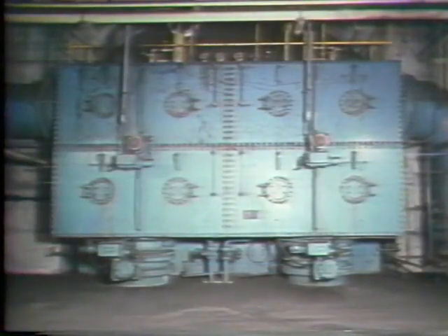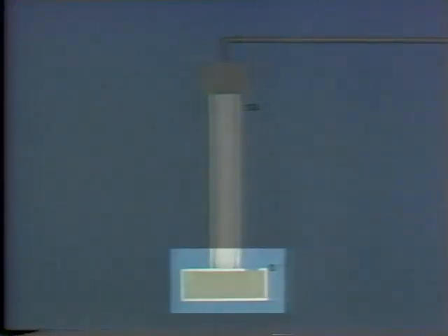Another common use of a mercury manometer is to measure vacuum in a condenser. It looks a lot like a barometer, except that one end of the manometer is connected to the atmosphere, while the other end is connected to the condenser. The scale reads from 0 inches of mercury at the bottom to approximately 30 inches of mercury at the top. If there is no vacuum in the condenser, the manometer will read 0, because the pressure at both ends of the manometer is the same.